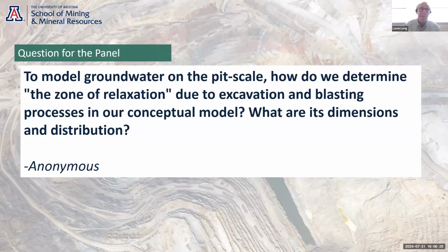And those are probably some of the best sources. There's some studies going on now where they're doing cross-hole seismic monitoring. So rather than trying to do it on a pit scale, they'll measure the seismic velocity between a couple of holes, maybe 50 or 100 meters apart, before and after an excavation of a slope. And you can get a much better idea of that. But you then have to relate that seismic velocity to a change in permeability, and that part's missing.